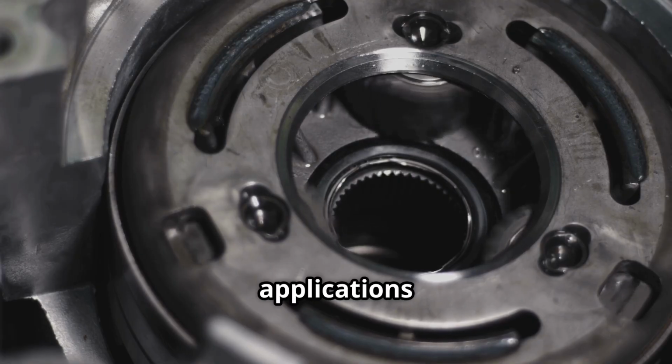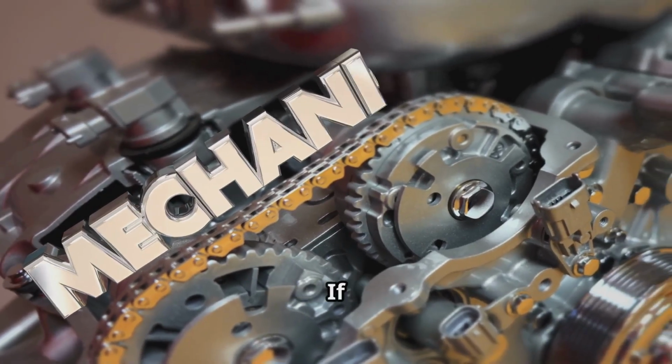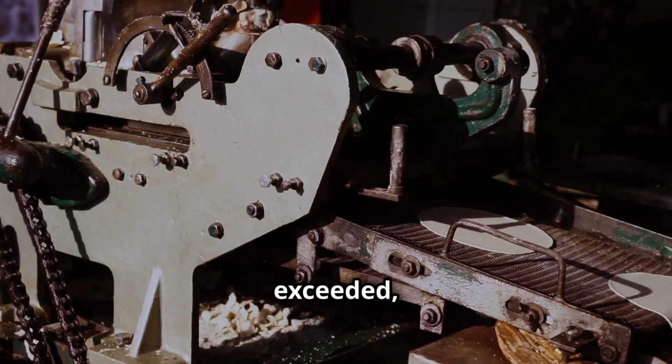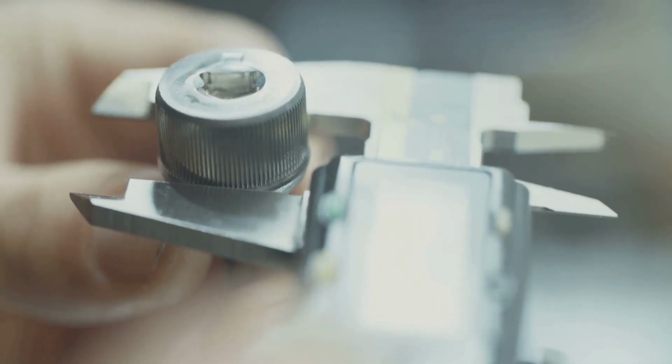Examples of machinery applications that operate under EHL are rolling element bearings, gear teeth and cam contacts where high rolling contact loads occur. If operating conditions such as speeds, loads, and temperatures are not exceeded, asperity contact may never occur due to this remarkable characteristic of lubricant and metal.